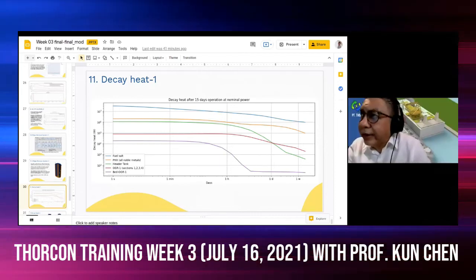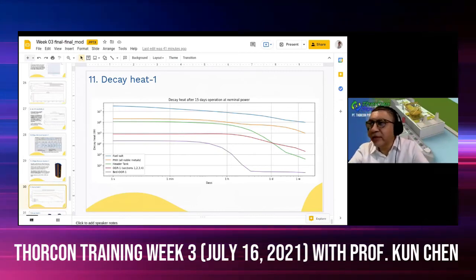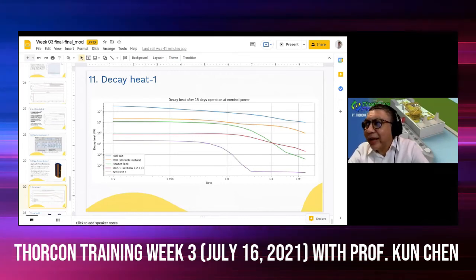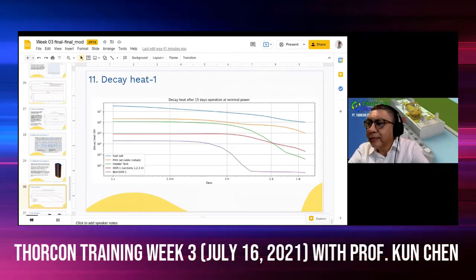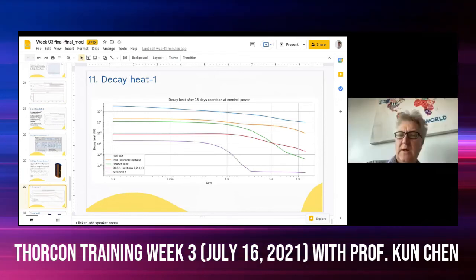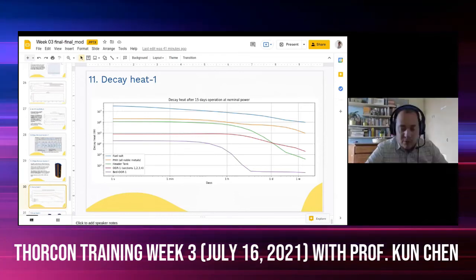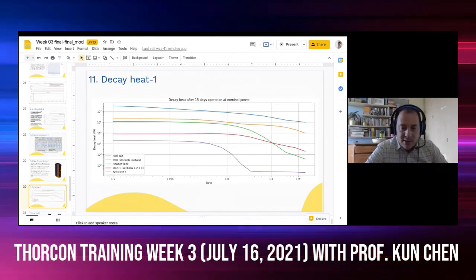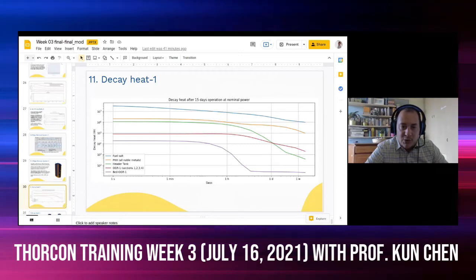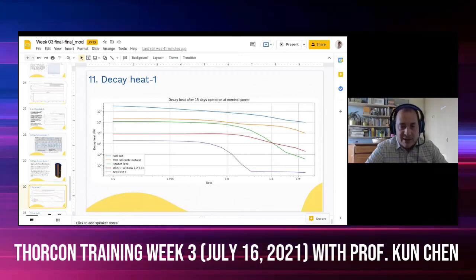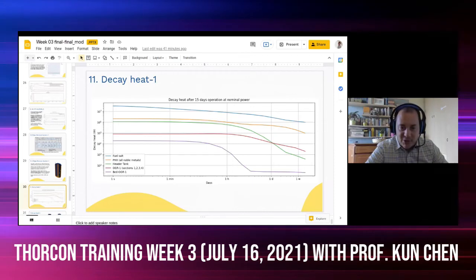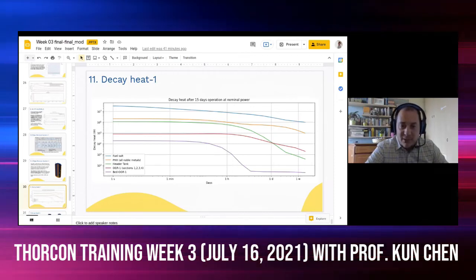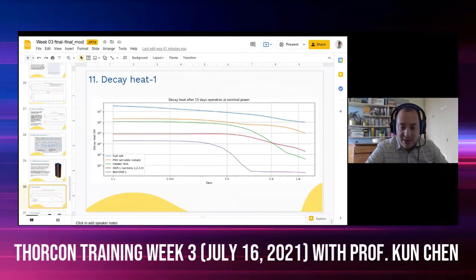Lars, the ramping rates, you said about 10% per minute. Is that equivalent to the performance of a gas plant? Approximately? Yes, it is in the order of what is requested in Europe of a gas plant, and actually in a connection demonstration, but not in standard operation. I don't know about other countries and specifically Indonesia, but in Europe and specifically in Italy, that's the maximum requirement for demonstration to be capable, but it is never requested in nominal operation.